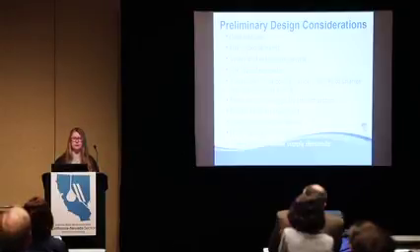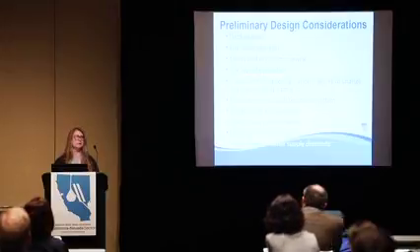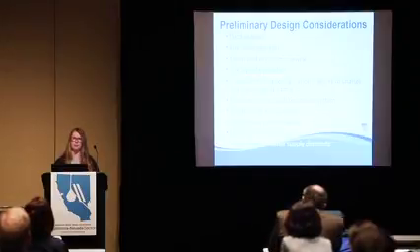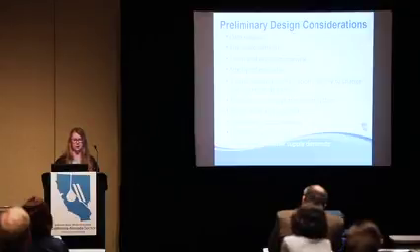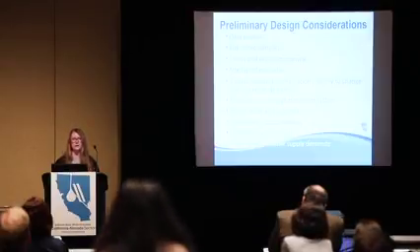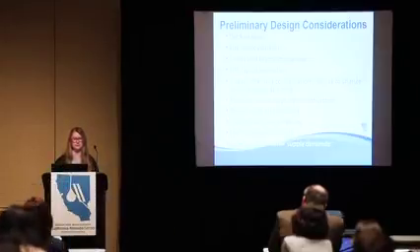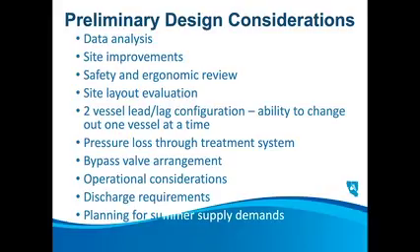We also completed a safety and ergonomic review, and I think this resulted in a great design for our operations staff. We looked at the height of the valves and the orientation they were in in order to be easily accessed, and we decided to install safety ladders on all of our units, which was the first for us. We had not done that in past GAC installations. We also looked at the site layout, which has to do with making sure that if you put these new vessels in, you still have room on your site if you ever have any repairs that are needed with the well.